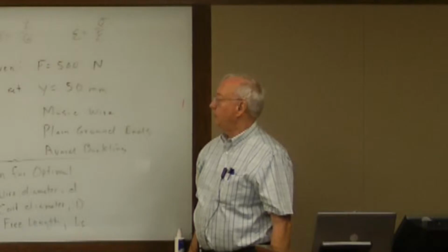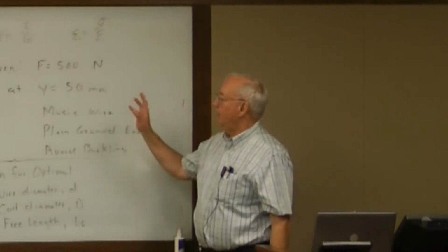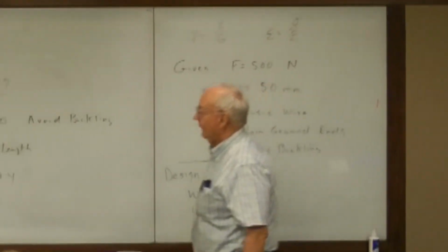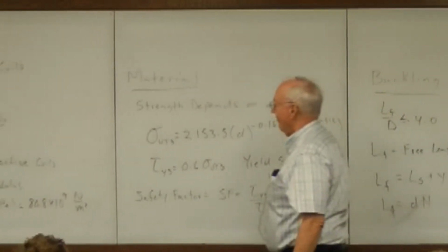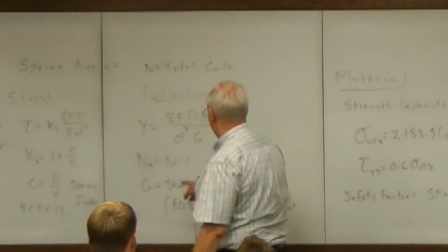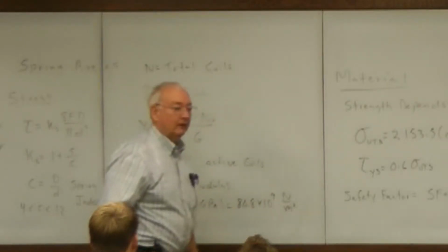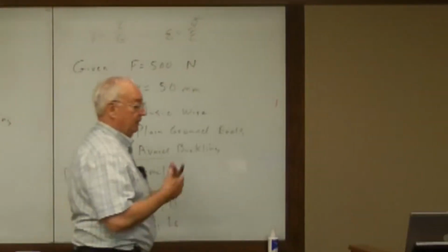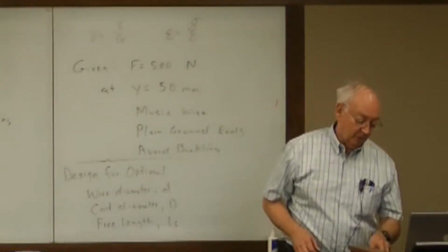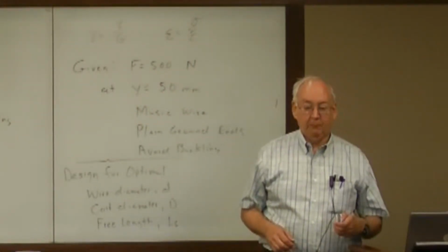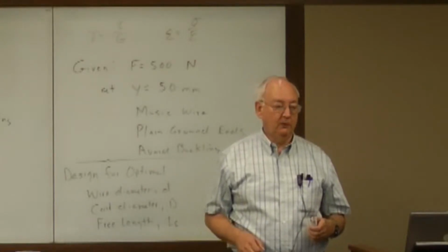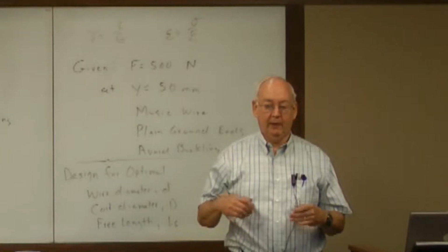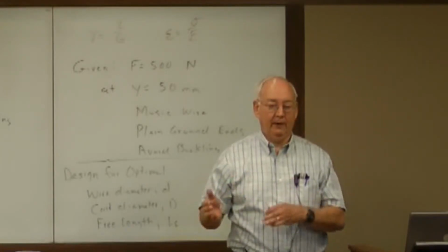When I design a spring like this and put everything together, one of the things that comes up is number of coils. That's important. So if the optimal design has number of coils being 8.43792, usually you don't make a spring to 8.43792, you make it either 8 or 9 or 8.5.